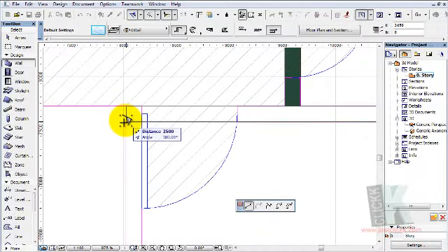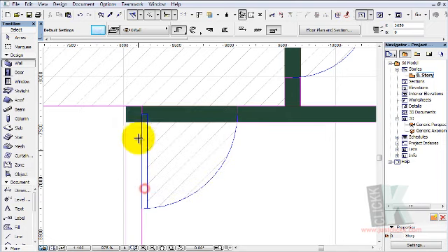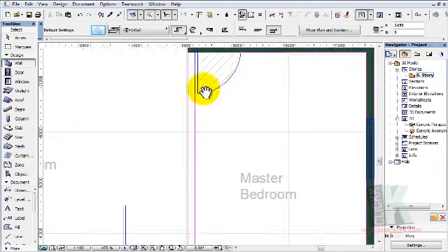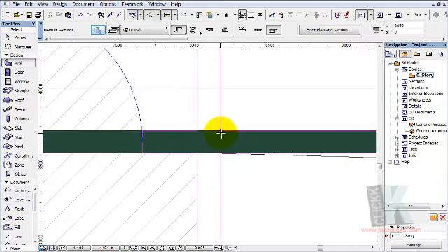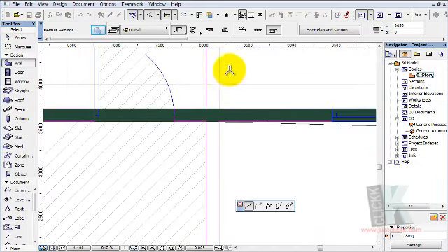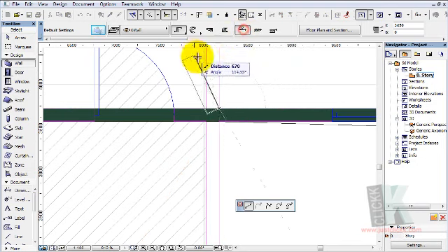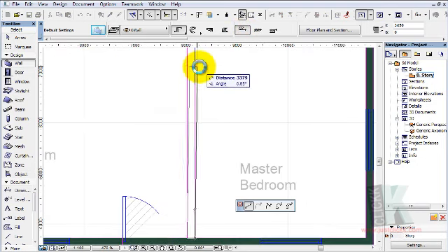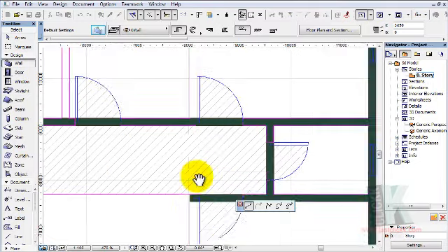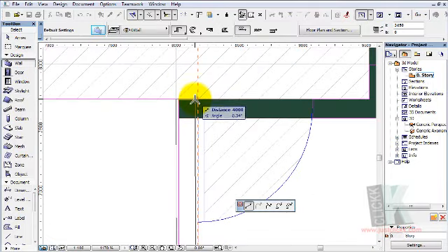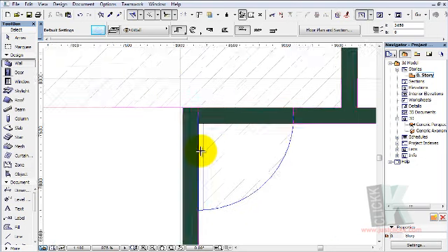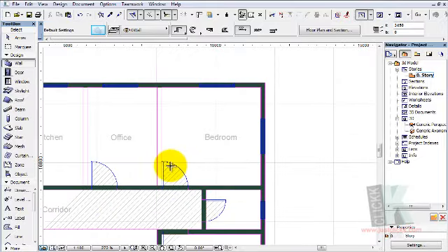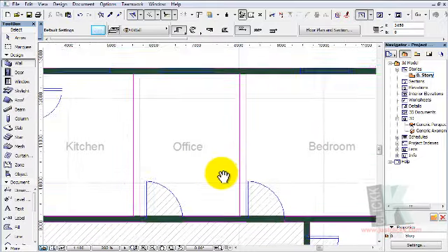You can hold down the shift key to make sure that your wall goes straight. And those are the tricks that I'm using. Okay, I picked the wrong choice. Okay, alignment, reposition. Okay, this takes me straight to this place. This is where this wall ended. Right click and I'll terminate this wall here. Okay, alright, I'm going to partition these walls now.